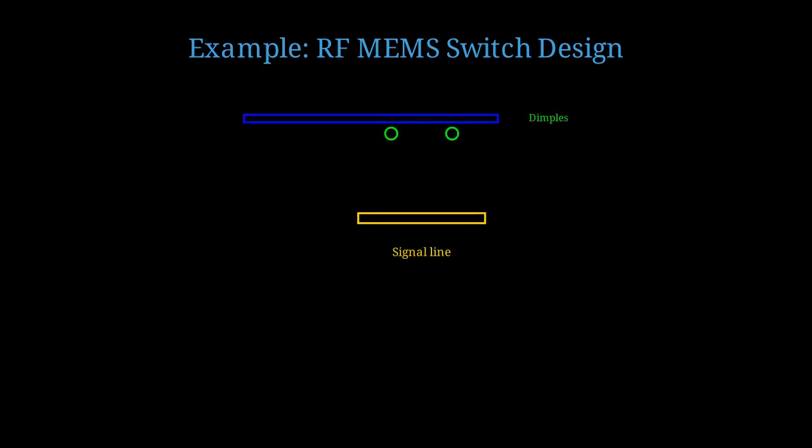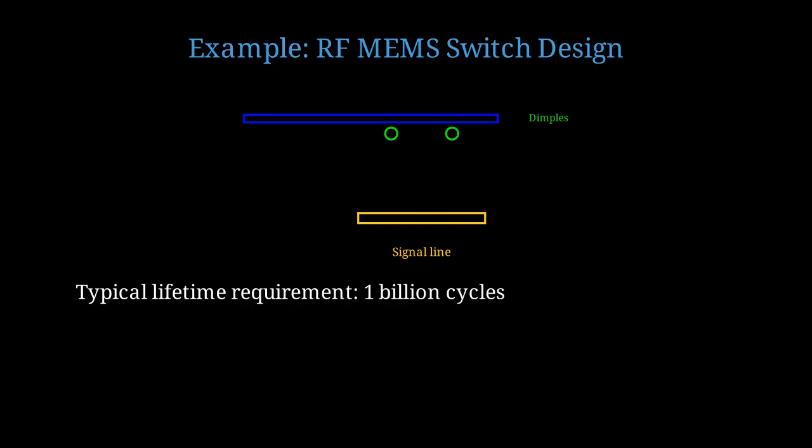When a voltage is applied, electrostatic force pulls the beam down. When voltage is removed, the beam must spring back up, overcoming van der Waals adhesion. Typical RF-MEMS switches must survive 1 billion switching cycles without stiction failure. This is extremely demanding. Careful design of all parameters is essential.